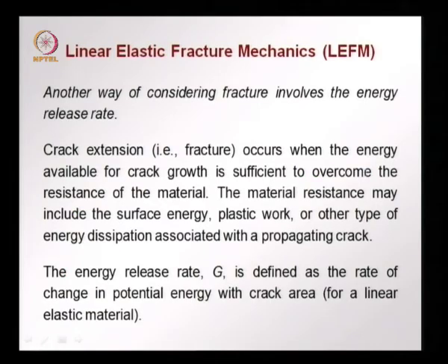Another way of considering fracture involves the energy release rate. Instead of the K1, which is the stress intensity factor, we can look at fracture mechanics in terms of the energy release rate. Whenever a new crack is formed, a surface is formed, and for this we require energy. So, all crack extension requires energy to be available for the crack growth to occur.